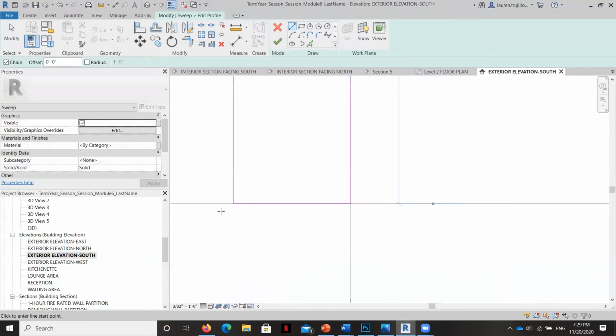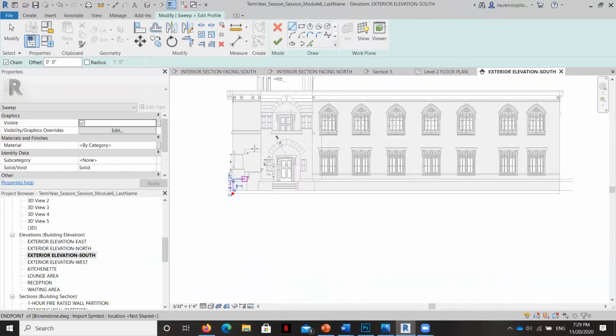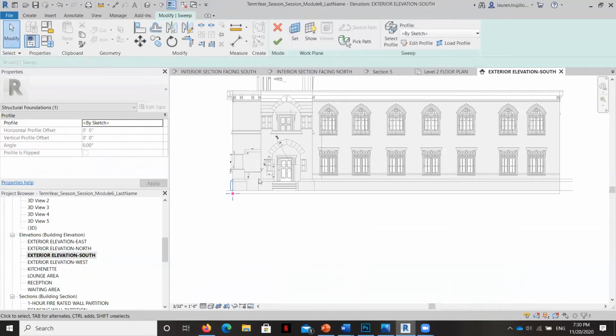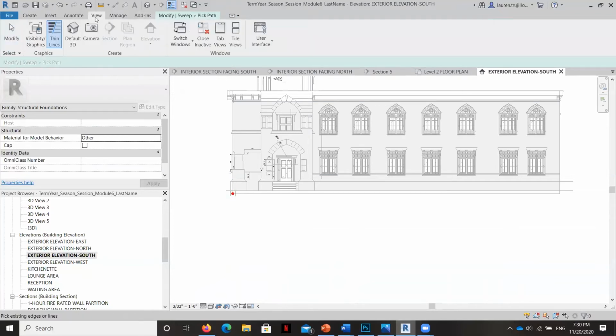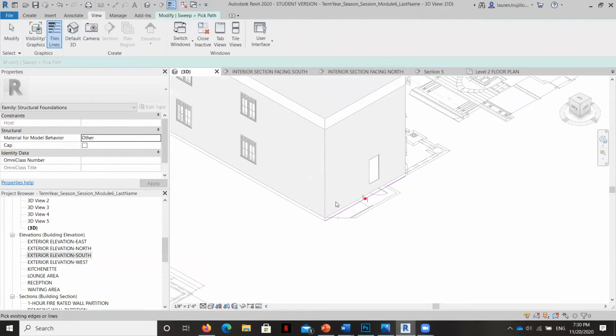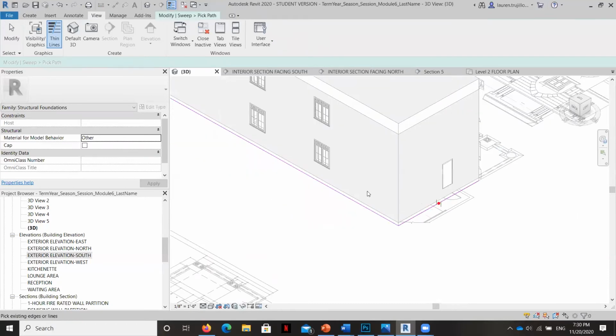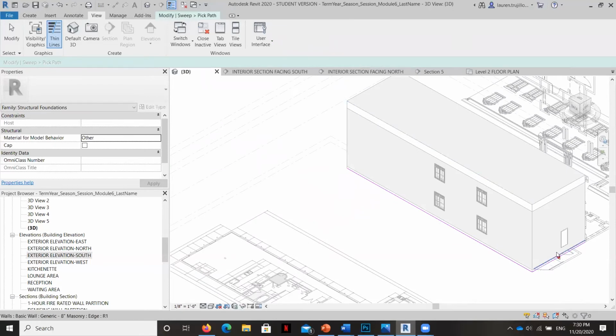Okay. Now, if I hit that checkbox, it's only going to extrude along that path on the bottom edge that we selected on that west wall. But I'm going to hit the checkbox now that says, okay, that's the profile I want. Then I'm going to go back to Pick Path, pick 3D edges, and then I want to look at it on a 3D view. And I'm going to grab the rest of the edges. But I started by just grabbing the first one because I wanted to control where that little shape showed up.